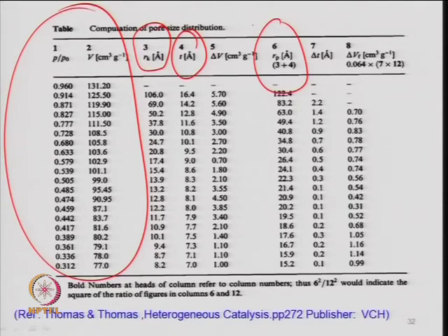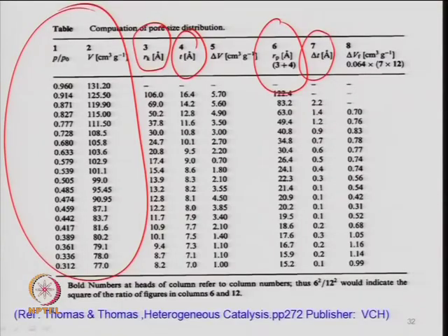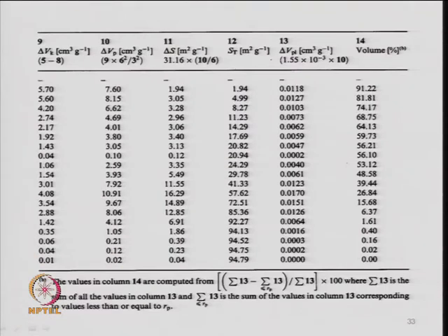and then the pore radius, that is the pore size distribution, and then we can find out the delta of that thickness between two changes, that is, how the adsorbed layer thickness decreases or increases when the pressure is applied, because when you are applying the pressure the thickness is changing. And then you have the change in volume between two successive pressure differentials. Likewise, you can find out the volume differentials between two radii r and r plus delta r, surface area, change in pore volume. So, plenty of information can be obtained from that P by P 0 versus volume.